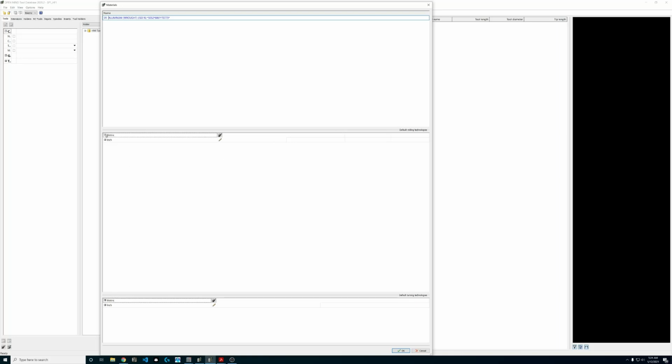I'm working in metric, so I'm going to select metric. Now, there's nothing here right now. We can even right click and you can see it's in the expand all mode, but there's nothing to expand. So this is when it comes back to our cutter material. Now, we're going to go ahead and apply a cutter material for this material type. Now you'll see that the thing that popped up is the SGS Series 43 MCR, because that's all we have inside of our database right now.